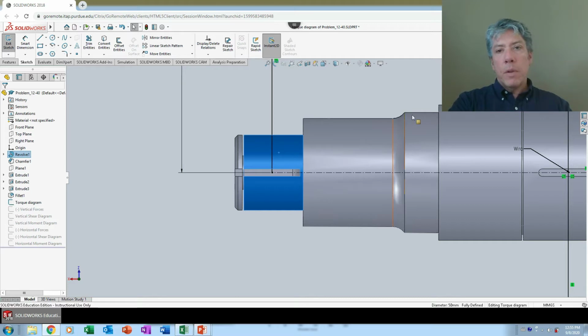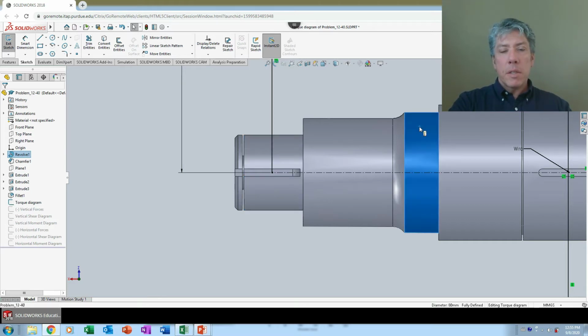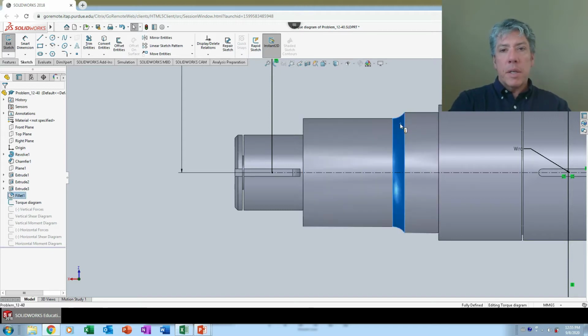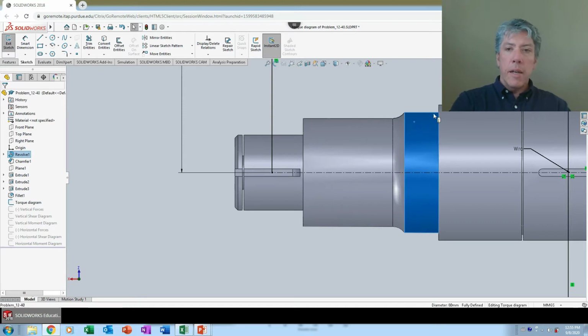What's this for? Well, remember the bearing slips onto this section of the shaft. So as I slip the bearing's inner diameter onto this shaft, I don't want to mess with this section, right? I don't want to have any real resistance there. And this nice, well-rounded shoulder should help locate the inner diameter of the bearing on its land here, and then of course this shoulder here represented by this line will stop the bearing in its appropriate position. So there's a few features.